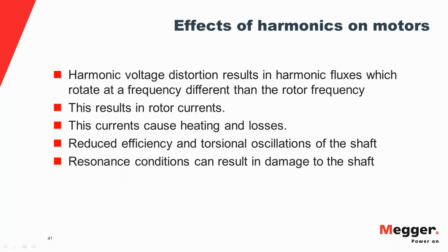Effects of harmonics on motor. Harmonic voltage is going to result in harmonic fluxes which rotate at a frequency different from the rotor frequency, which rotates at close to the fundamental frequency. So the frequency difference in the interaction between the flux and the conductor is going to result in induced currents. These currents are going to cause heating and losses.